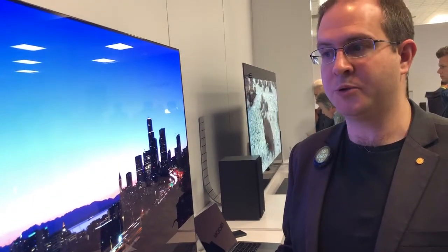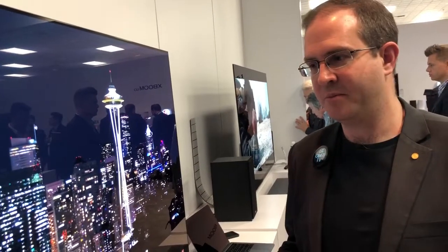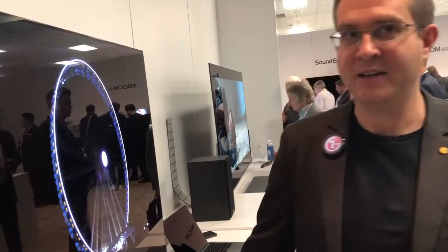In the past, on the 2017 models, the Alpha 7 models, they used a global color saturation boost to compensate for a desaturation caused by adding white, but that desaturation wasn't global, so using color boost is not really the right way to do it. It's not obvious, because even if you look at competitor products, everyone has a color slider, and in the UI it will still look like there's no color boost. But if you got down to the chip level, you'd see there is, because if there wasn't, you'd see massive desaturation. That's on the processing chip, driven with firmware as well. That global saturation boost is done by, as far as I know, all manufacturers to compensate for the desaturation of the white OLED.